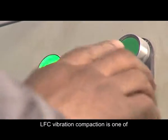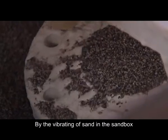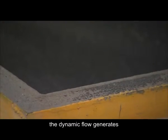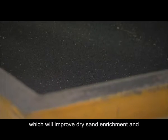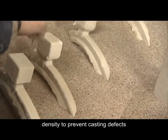LFC vibration compaction is one of the key processes. By the vibrating of sand in the sandbox, the dynamic flow generates, which will improve dry sand enrichment and density to prevent casting defects.